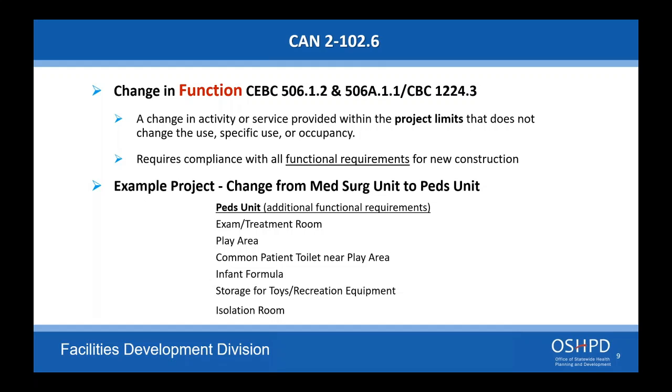This has been a request that we must update the corridor as well as the patient room so that the fire rating is corrected, i.e. if the existing room is 75 CFM positive but there is no requirement on a rated corridor, do we need to make the room neutral as well as change the offset on the corridor so that it doesn't change the overall hospital?